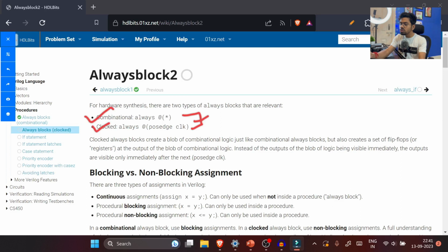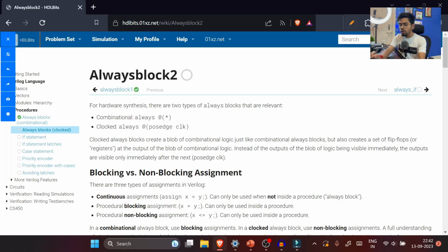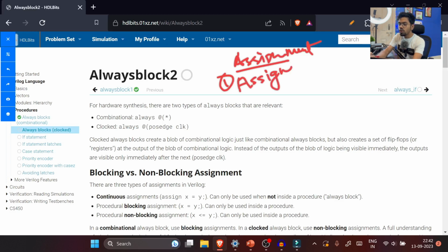Anytime we use assignment in Verilog, we have three types of assignment. You have already used two types till date. We're going to introduce the third one, which is called a non-blocking assignment. I'll come there, don't worry. The first type is a continuous assignment, which is achieved using the keyword assign. If you write a equal to b, then for sure b will become a, where a must be a wire type. If a is a reg type or any other type, you will get an error. So that's why a needs to be a wire.